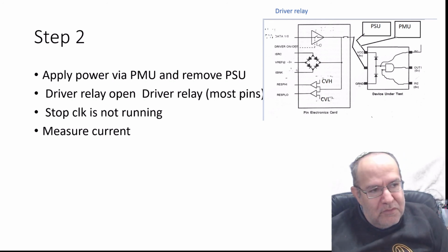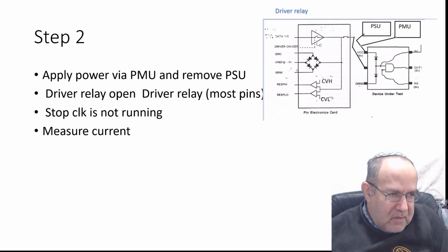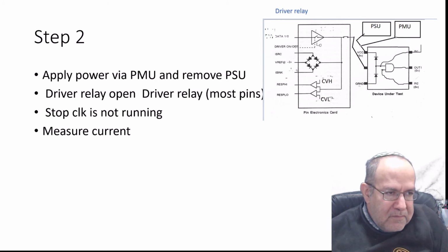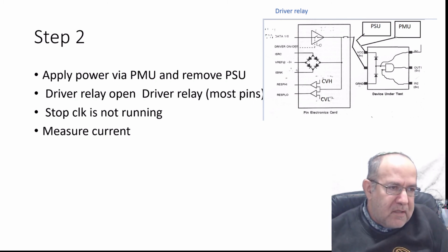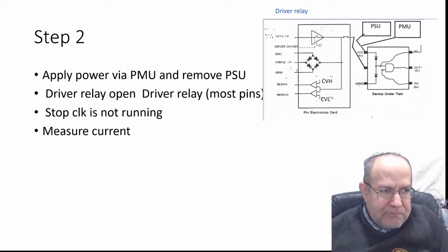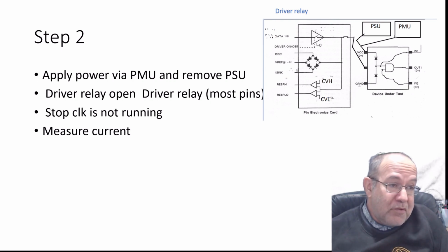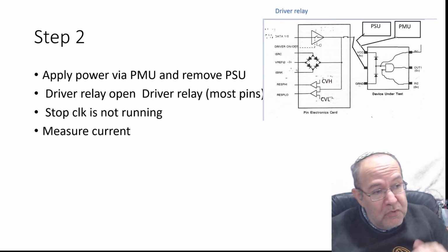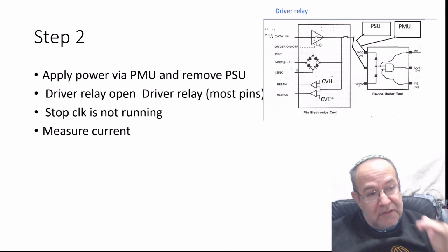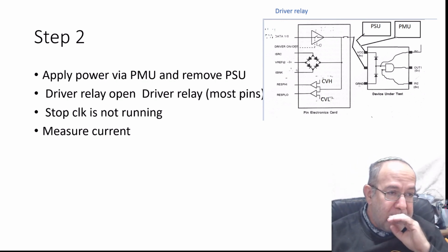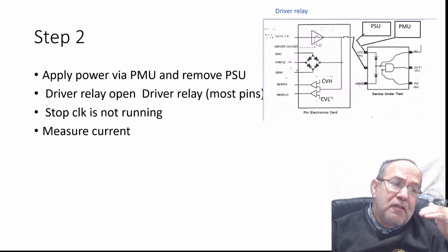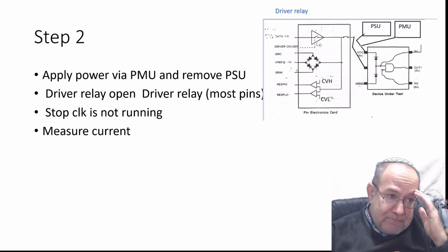If you have 10 dies down the line, you're going to measure this die with respect to the 10 previous dies. You don't know the next dies, but you are going along and using this to move your current limit up and down, so that you're finding the dies which are exceptionally high compared to the rest of the dies in the wafer.